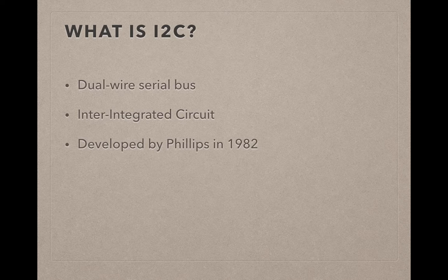Combined with the 2 wires for power and ground, I2C enables communication across multiple chips using only 4 wires. This means that on our Raspberry Pi we don't have to use up all our precious GPIO pins to drive directly attached devices, but rather can send byte commands from our Pi to a chip or several chips, which will drive the device for us.